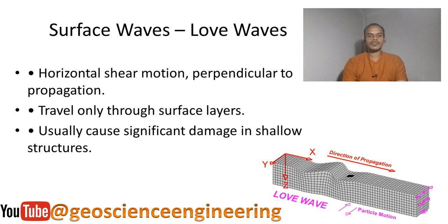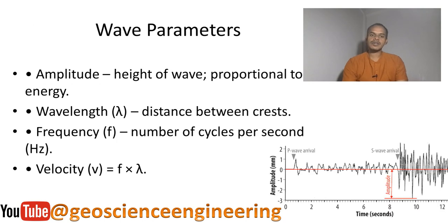We'll also discuss the S waves, then the surface waves, Rayleigh waves, and most important, we have to discuss the wave parameters, because when you go for an earthquake study, you need to find the amplitude and also the velocity and other properties of the seismic waves. So we'll discuss amplitude, and then how to measure the amplitude, and what kind of software is used to directly give you the maximum amplitude value, and then the velocity.